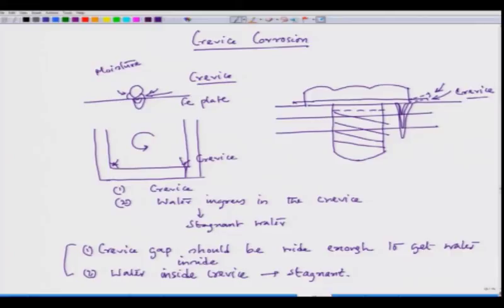For example, if we have dirt on the bottom of the steel container, it is always better to get rid of it. That is why a water container should be cleaned from time to time, and the cleaning allows the dirt particles to be removed, which finally reduces the crevice attack.